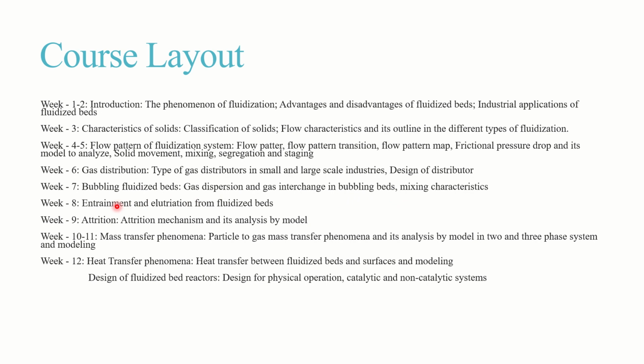In week 8, we will be dealing with entrainment and elutriation from the fluidized beds. Week 9 is the attrition mechanism and its analysis by model. Weeks 10 to 12 deal with the mass transfer and heat transfer phenomena taking place inside the fluidized bed. The fluidized bed is found very useful in terms of its mass transfer and heat transfer properties, because in packed beds there are chances for hotspots to form when dealing with highly exothermic reactions, which can be minimized when we use fluidized bed reactors.